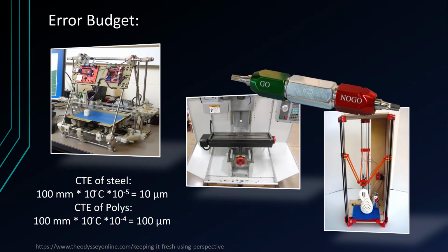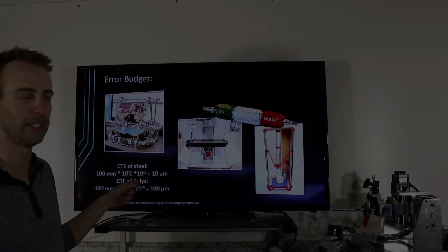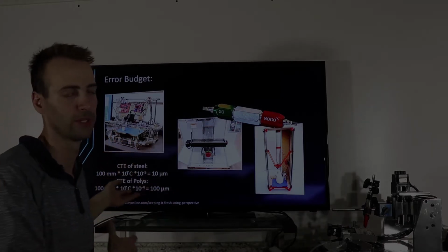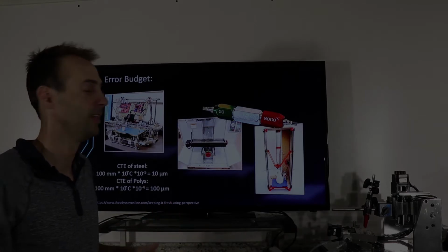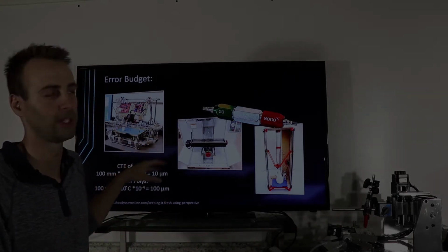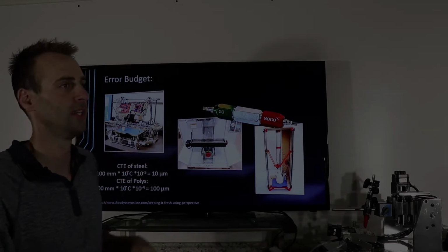So this is crazy. Anytime I see plastic on a machine that's trying to get tolerances anywhere near a thousandth or 25 micron, it ain't gonna happen. Not unless it's a super stable environment and it's very carefully engineered. So let's just look at this Haas machine, all right?